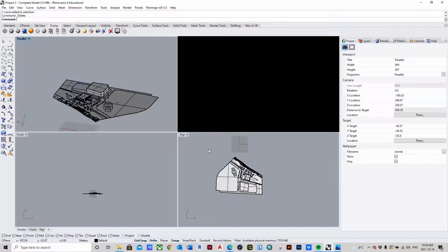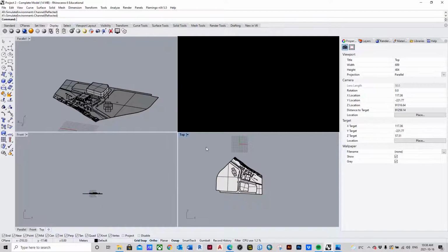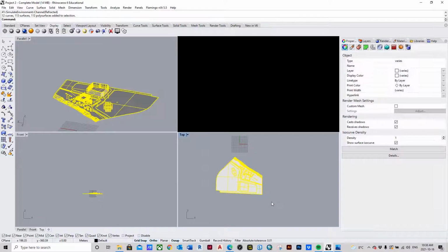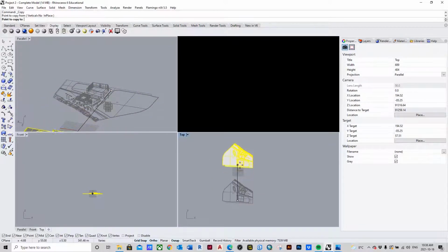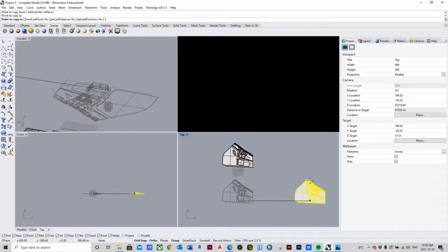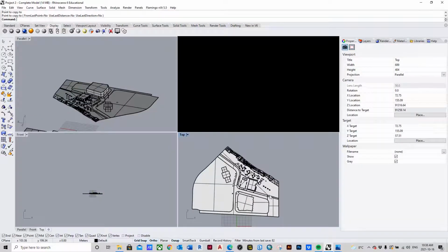The first thing is we're going to left click, hold and drag over the model. Then we're going to create a copy. So we're going to go Control C, or if we want to, we can use this copy tool. Actually, this might even be easier, so how about we'll do that instead? Left click, pull, hold down, drag over the whole model. Move over here to copy. Point to copy from. It doesn't matter, but let's just grab it from somewhere here. And we'll copy, and then, because we're happy with that copy, we're going to hit escape to finish that move. So now, here's what we've got.